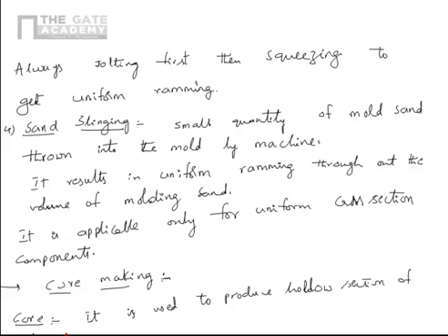Once you insert the pattern in the sand mold and fill it, how do you remove it? You can't, it's not like breaking the sand. Suppose you prepared a cylindrical wooden pattern, kept it in the mold and filled the molding sand; the molding sand will go inside the cylinder also. You can't remove it without breaking the mold, and if you break the mold, you can't prepare the casting.